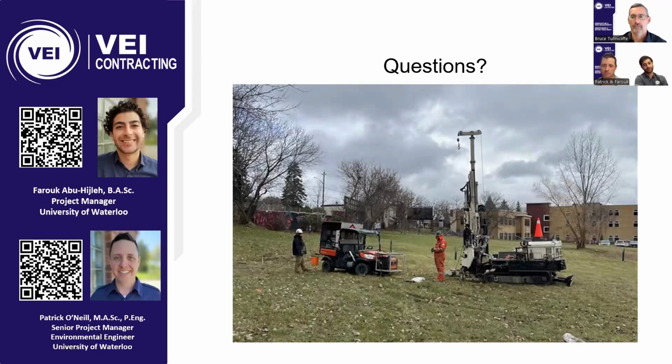So it matters. And the typical way the dewatering assessment's done is they'll build in so much factor of safety. You'll build in highest water table, your thickest sand aquifer, your maximum drawdown. You get your K, your highest K that you've observed on the site. You do that, you estimate Q, and then you'll apply a factor of safety of 2, 3, 4 on top of that number when you estimate Q. So you're building in so much redundancy in the Q. When it comes to us as contractors, I get a number that says it's 2 million liters a day, for example.